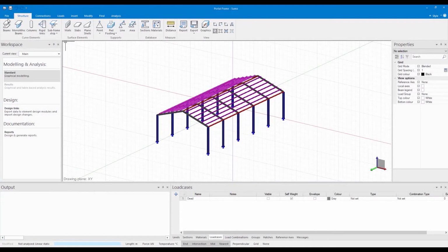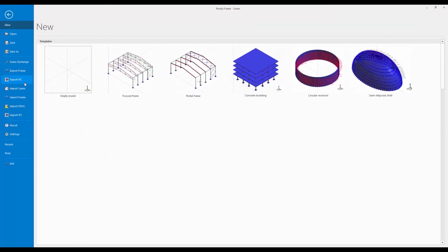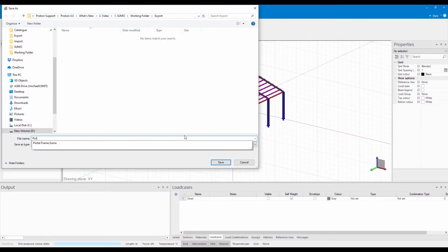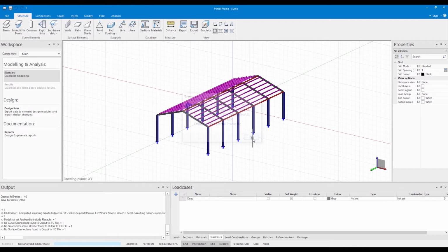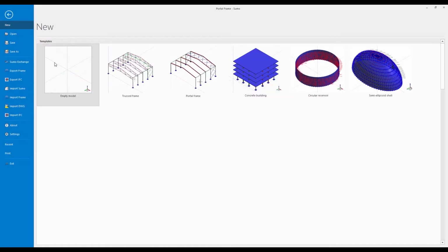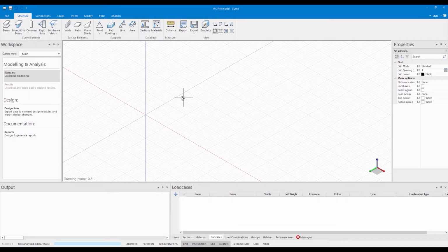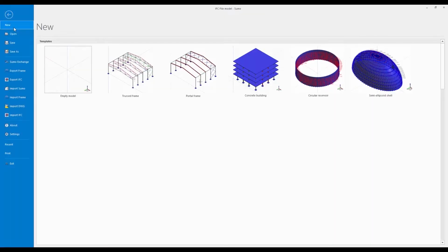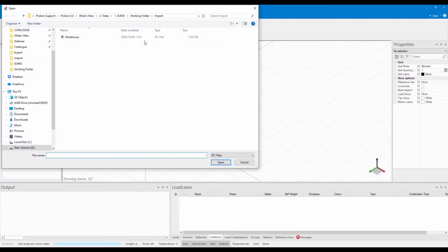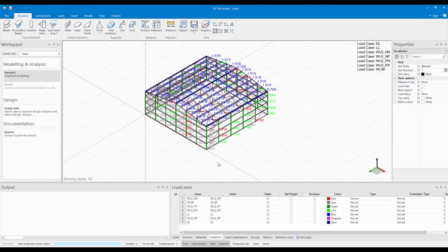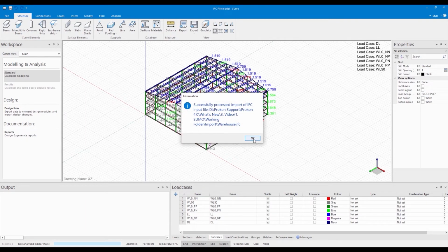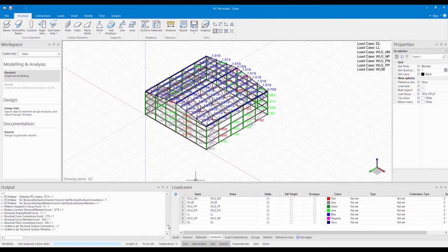Sumo Structural Analysis has further developed in order to maintain its compliance with the Building Information Management strategy by becoming compatible with industry foundation class files. The module now allows the importing and exporting of structural analysis IFC subsets with other third-party software. To ensure a seamless integration between third-party software, when exchanging structural analysis IFC subsets, the module displays an information box indicating the success of the import or export and an output dialog box which supplies the user with a list of detailed information regarding the exchange.